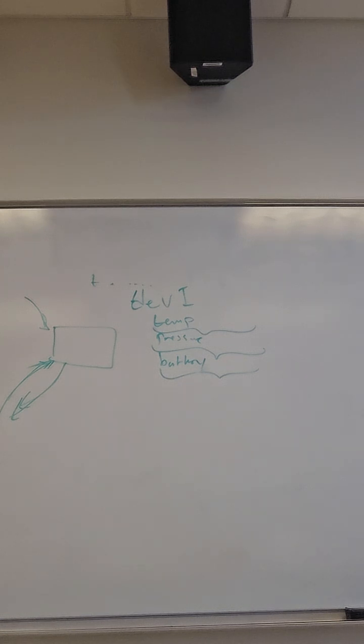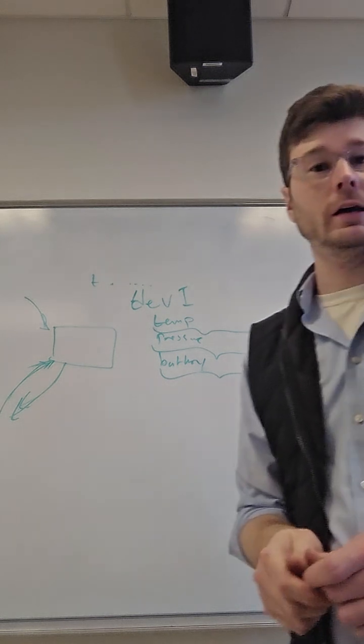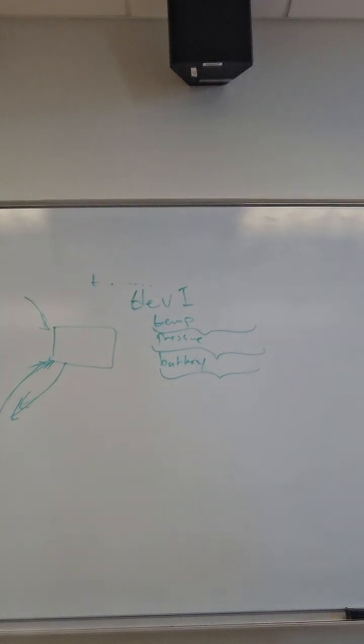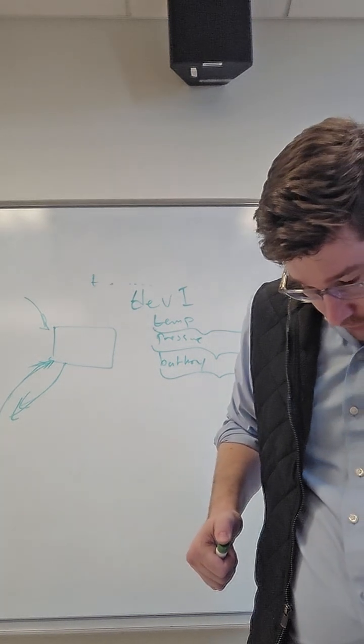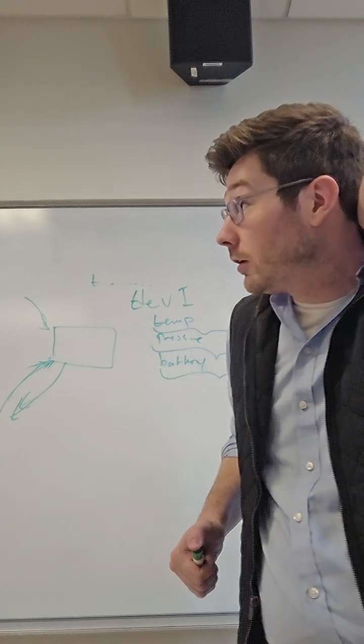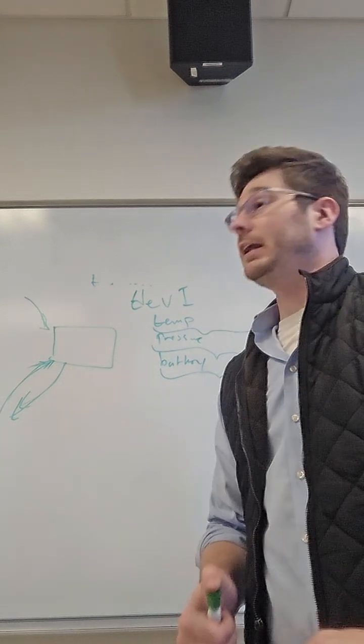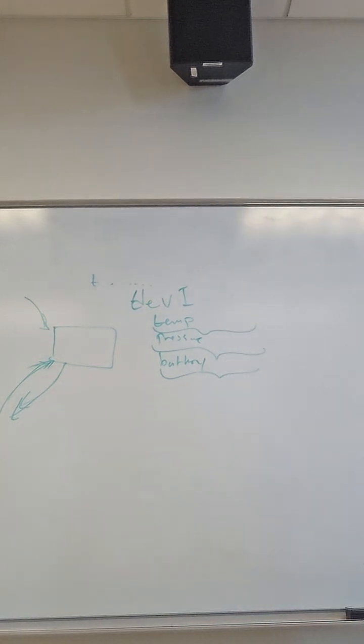These are our ESP32s and our Raspberry Pis and things like that. And how do we get that really leanly into our big hefty cloud server as simply as possible? And the way that can be done is through MQTT. There's definitely more ways to do this, but this is just one of the standardized protocols that enables that kind of communication.